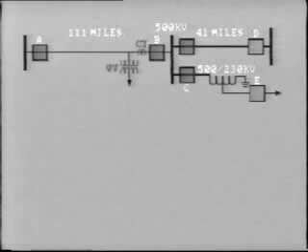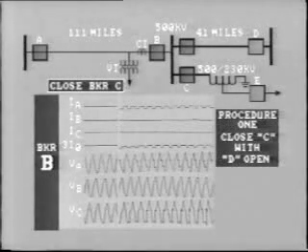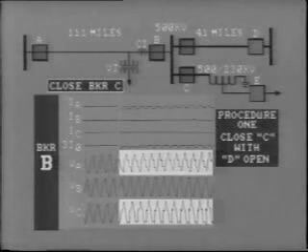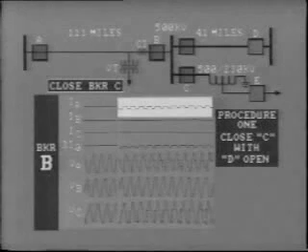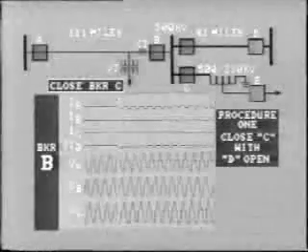The oscillograph has recorded voltages and currents on the line side of breaker B at the transformer substation. Here we show the traces for procedure 1 with breaker D open. This looks quite strange. Voltage VA on the A phase shows some distortion, also VC to a lesser extent. And this current IA must represent transformer magnetizing current. Your workbook explains why only one phase is affected.